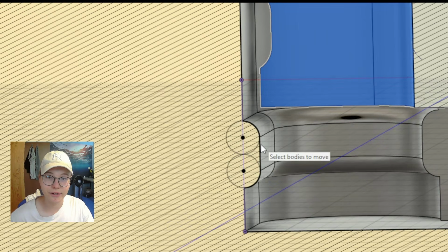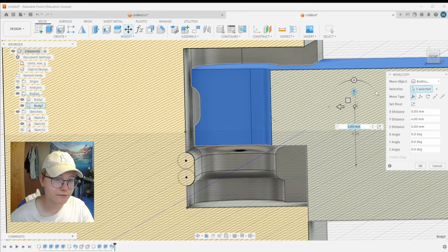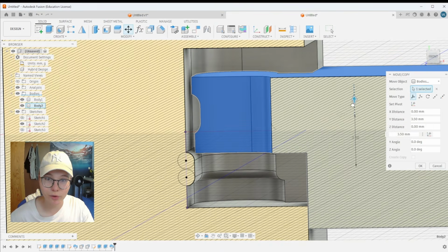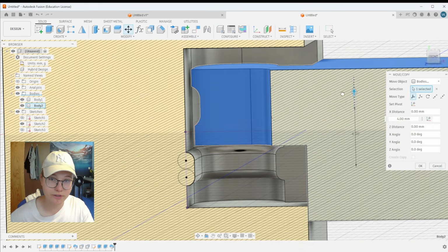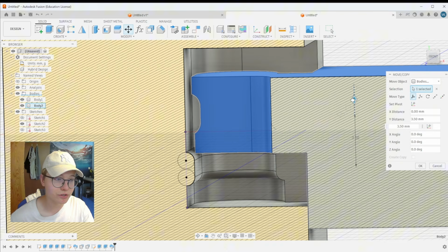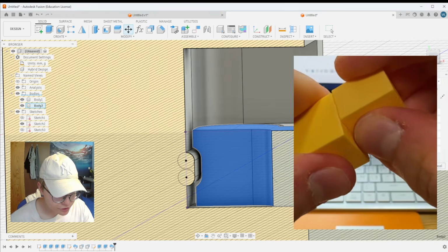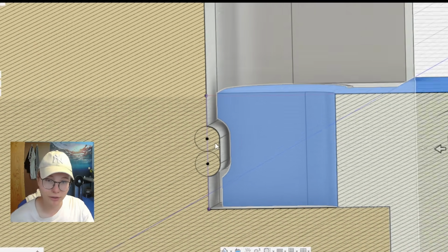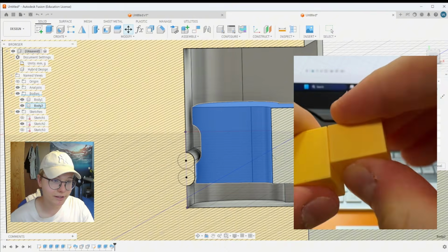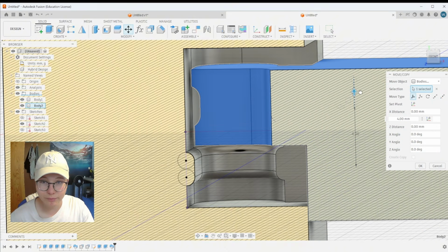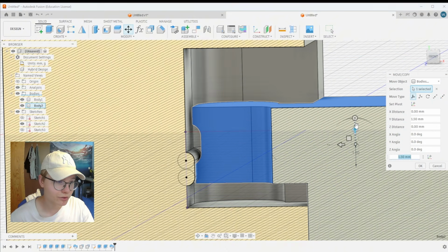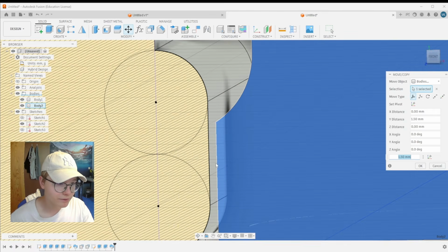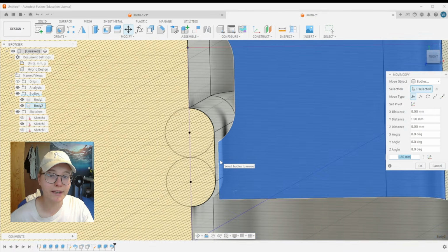And as you can see right over here, when the press fit starts, when you start pressing it against over here, it meets with the body. So this is where the snap is created. And then once you reach the bottom is when it stays together. So like this, it's locked in, but when you are inserting it and taking it out, it makes that sound of snapping because over here it meets with these two walls, and that's what creates the snap.